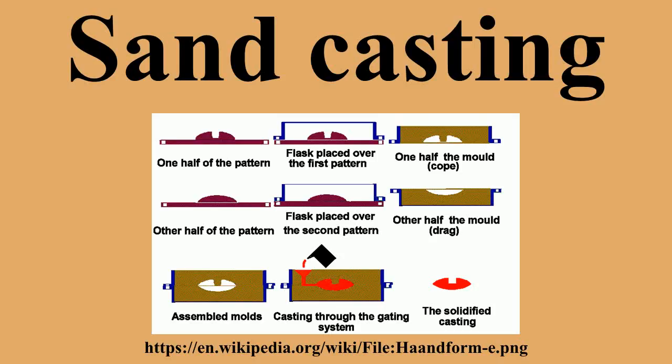Sand castings made from coarse green sand impart a rough texture to the surface, and this makes them easy to identify. Castings made from fine green sand can shine as cast but are limited by the depth-to-width ratio of pockets in the pattern. Air-set molds can produce castings with smoother surfaces than coarse green sand, but this method is primarily chosen when deep, narrow pockets in the pattern are necessary, due to the expense of the plastic used in the process.